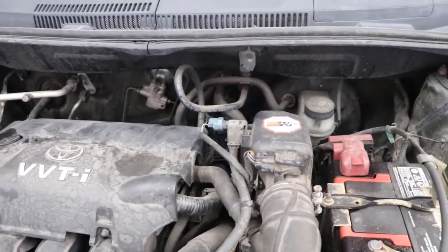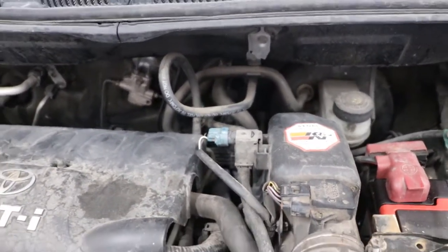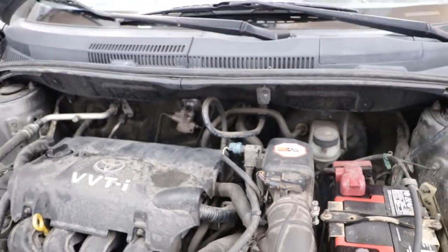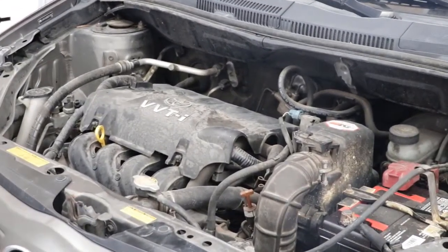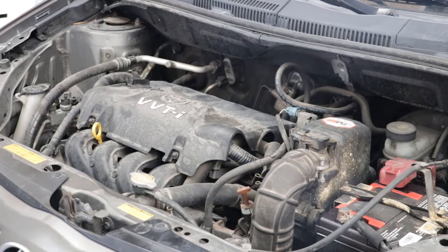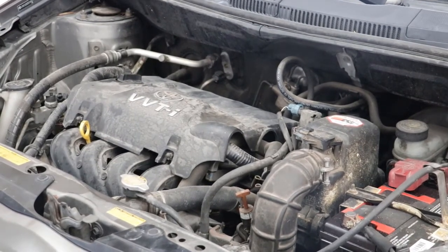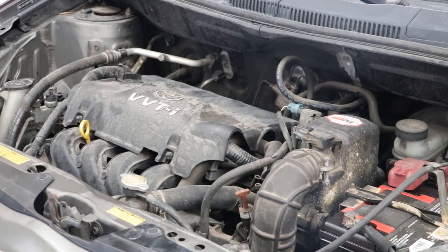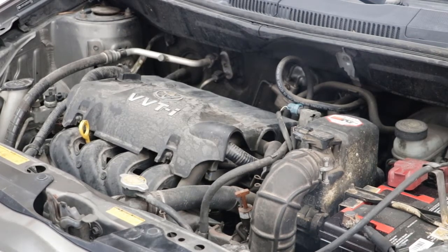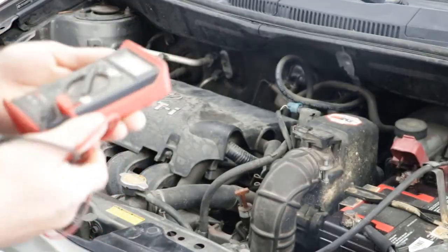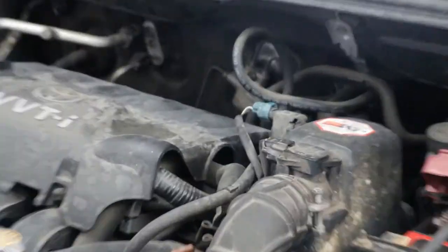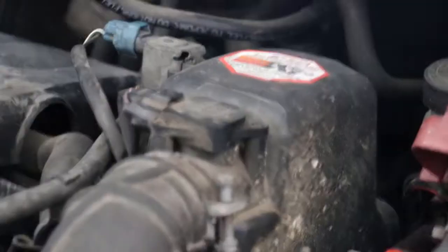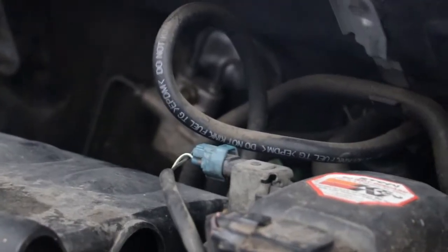And yeah, so let's go ahead and test the valve here. I'm going to take it off. I'm also going to get my voltage meter, and with the voltage meter as well, what I'm going to do is, after I unplug it, I'm also going to test to see if the voltage is coming strong from the computer to the system here. And once we get it going and tested, we'll know whether or not the computer is sending it. So we're kind of troubleshooting, knocking out whether or not some problems exist or not. First thing we're going to do actually is we are going to unplug the sensor here and go ahead and do a test on the sensor and see how it is.